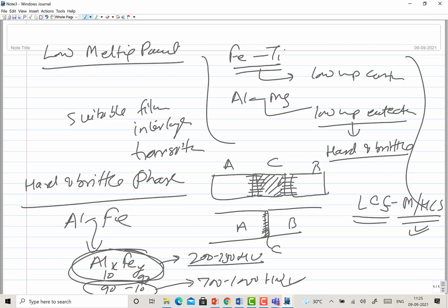So this is one aspect: when you are working with low carbon steel and medium or high carbon steel, the primary difference in hardenability will lead to a difference in the ease of joining of these two metals. It is possible that one metal is already soft and ductile, and the other is hard and brittle, so you may need a little preheating.